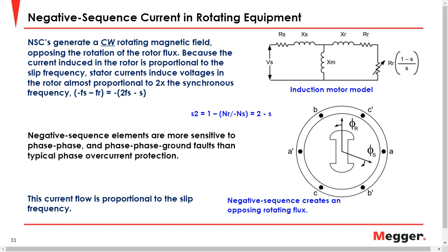So whether that be through saturation of a CT, or how CTs saturate differently from one another, that can show up as an imbalance, unless you have a true linear relationship between your primary, your secondary, your actual values.